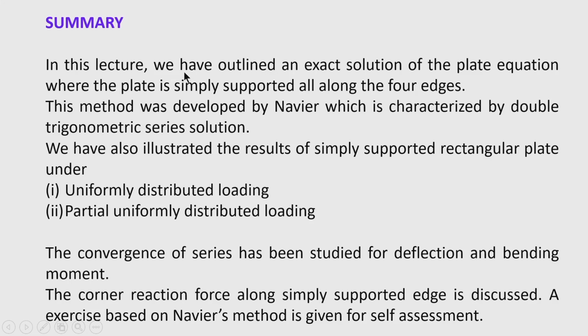So, in this lecture we have outlined this exact solution. Navier's method is used, and it is characterized by double trigonometrical series, and the method is illustrated by a simply supported rectangular plate with uniformly distributed loading and also partially uniformly distributed loading. The convergence of the series has been tested for deflection and bending moment, and it is concluded that for deflection the convergence is rapid in case of Navier's method. Only the first term gives reasonably accurate results.